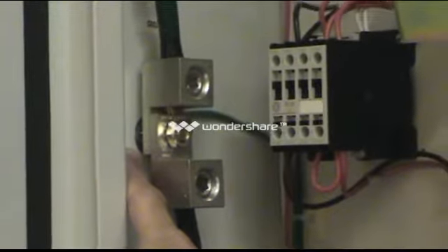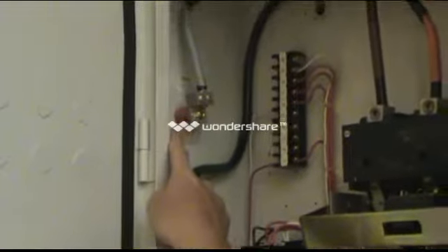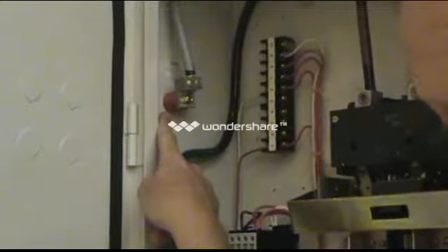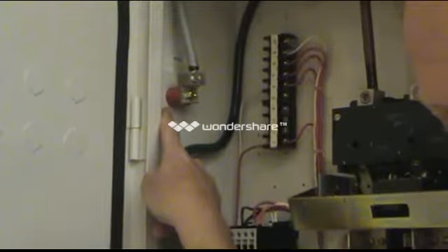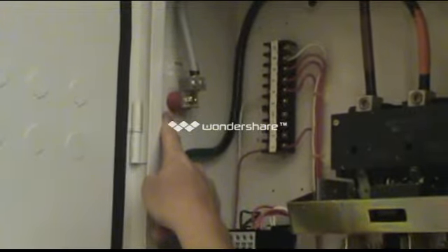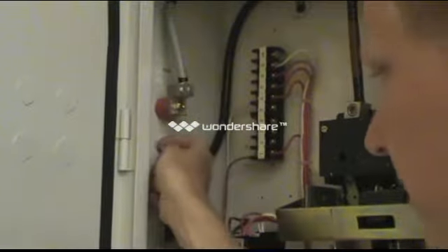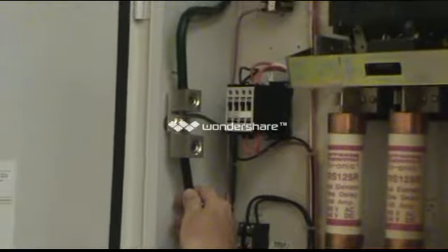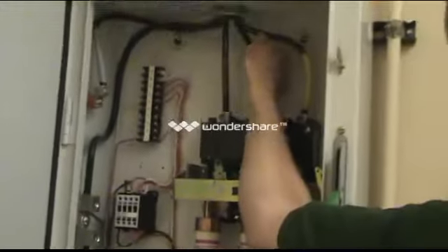All right. Is a neutral isolated from ground? Well, let's move on up. There's a neutral. It is on an isolator, so that is good. All right. Can you verify that the connections are not loose, discolored, pinched on the installation? This is going to be our tug test. So we'd go through with all power off, of course, and give them a good shake all the way through. This is something that most FEs don't do. So this side is all good.